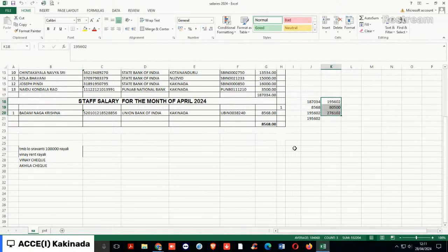And we can see the short bar lengths, almost without any end anchorage. Even a 135 degrees hook is not there. It is not 75 mm. It is not 10 times the bar diameter. Even for normal gravity loading, the minimum requirement of the end hook is 6 times the bar diameter. If it's 135 degrees, I think it's 8 times the bar diameter. Six times the bar diameter is not there, even for gravity loading. The main bars will fail under gravity loading also if the stirrups are like this.